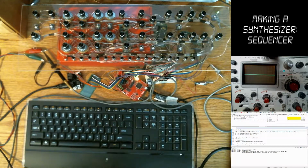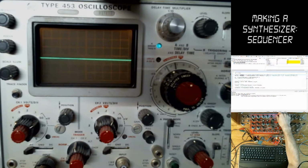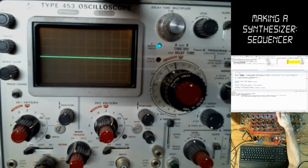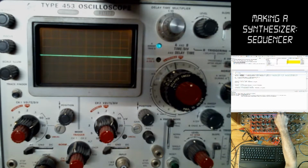And you can see as I do that, okay, so you can see what happens when I adjust the low pass filter. It gets rid of those sharp edges. Those sharp edges are only possible with really, really high frequency content signals. So as you cut away the high frequency content, you essentially smooth out what it looks like.